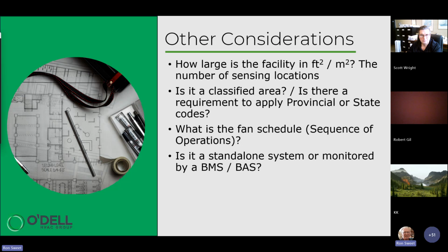The underground parking garage's gas detection system has probably been activated, and of course, the ventilation fans are going and the motorized dampers are open, so there's a constant feed of oxygen. The firemen would like to know that, and they'd like to have the capability to turn that system off so it's not feeding oxygen to that fire. So knowing that you want two systems to interface at the completion of your project, talk about it up front. There are ways that that can be accomplished.